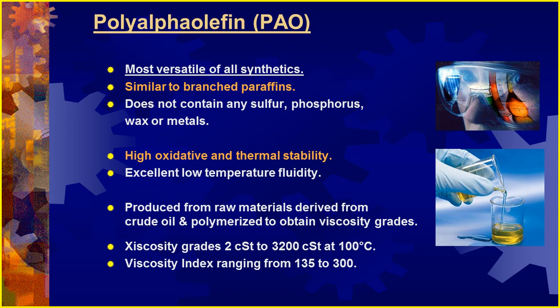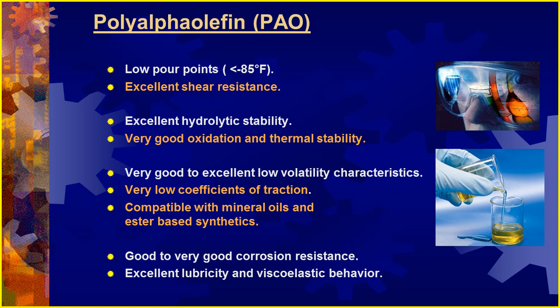The most premium use is what's called PAOs or polyalphaolefins. The branches within the paraffins and the molecules work together. It has one of the greatest oxidative and thermal stabilities that are capable. It's very highly used in many aerospace and other performance applications. It has a low pour point.